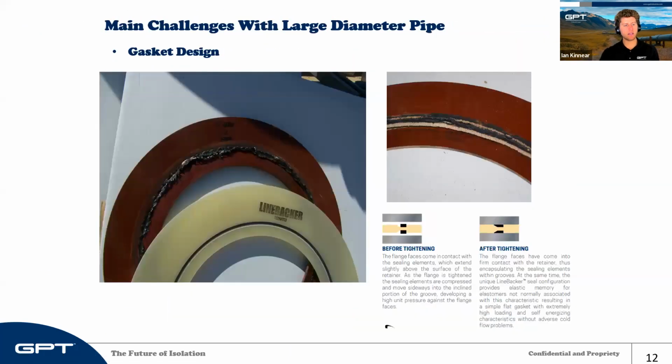So what you'll see here, that groove is specially designed so when that seal sits in it, we need that seal to compress once the flanges are torqued. That compression is what's going to make your seal. But you need that seal to be able to compress into something. If this design doesn't have a groove that the seal can compress into, just like this, it might flow over the edge, and over time it's going to run that seal out, and it's going to create a leak path.